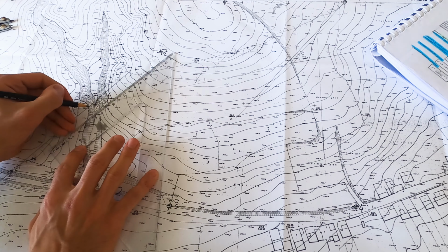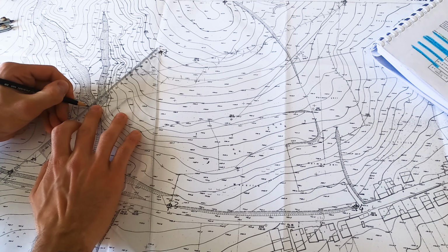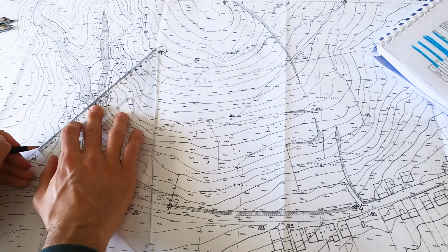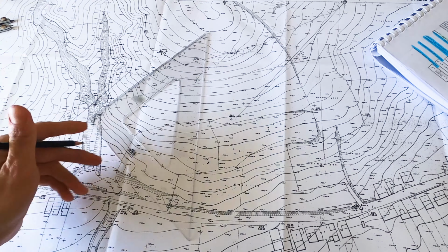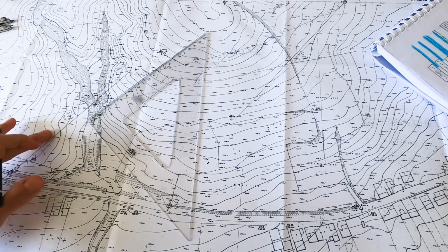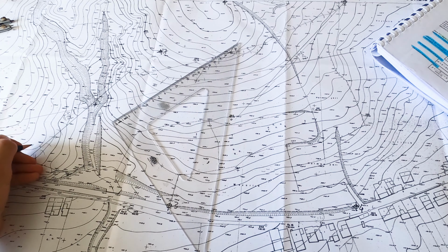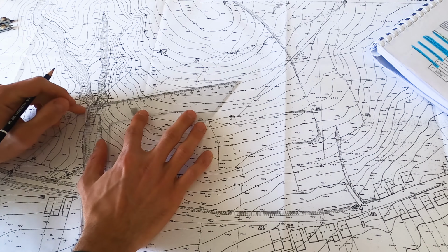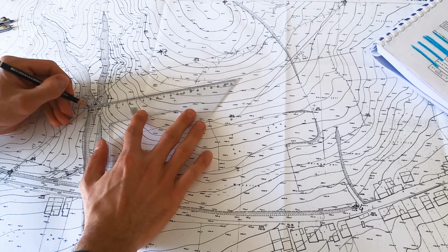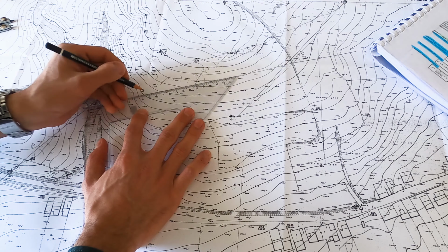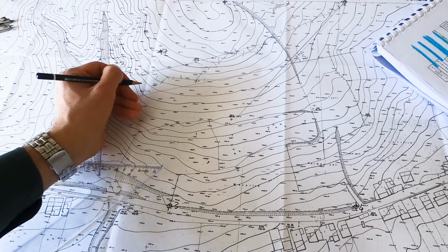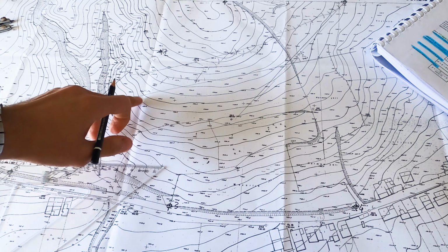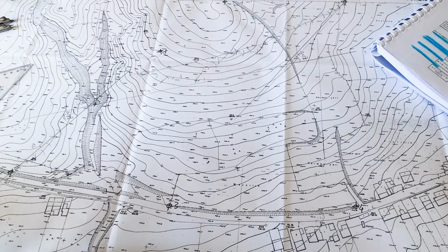So from the intersection point in here, this is 8.4, and on the tangent, it will be this point. This point is known as the tangent to the circular curve. So we can say TC, tangent to circular curve. By the same manner, on the other direction, we start from the intersection point and go 8.4 centimeters. This point is known as CT, because circular curve to the tangent of the horizontal alignment.